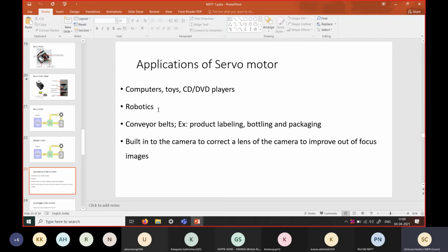In leg robotics, these servo motors are very useful because they are not just continuously rotating links. We just need to move the link from a certain angle to a certain angle repeatedly. As the servo motors have their own electronics, we don't need to worry about how to maintain the position. We just need to communicate to the motor which position we want from time to time, so that the controller will itself take action and maintain the position and speed of the motor accordingly.